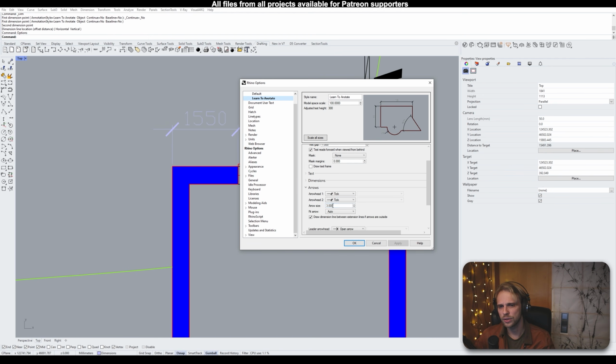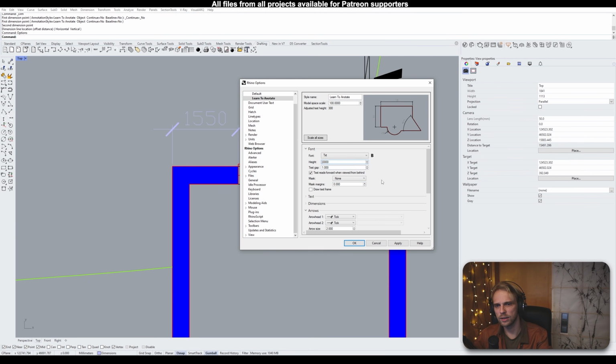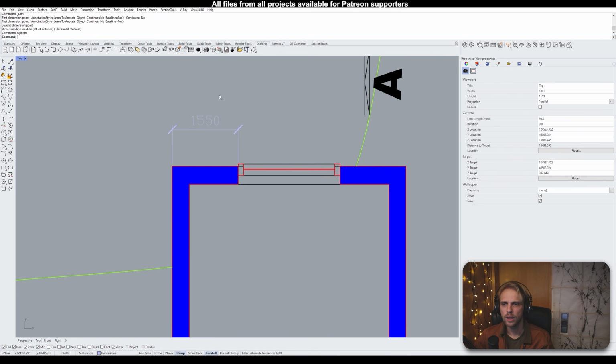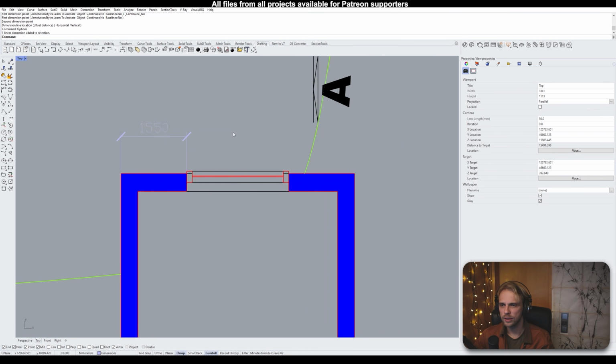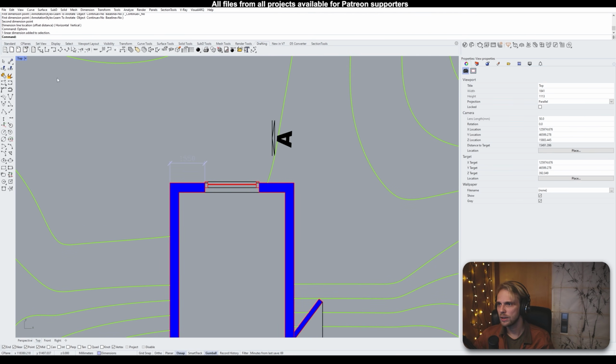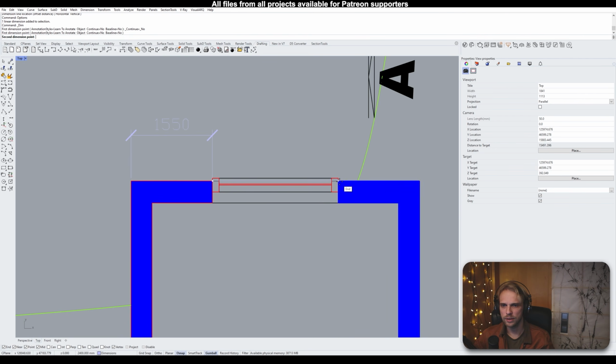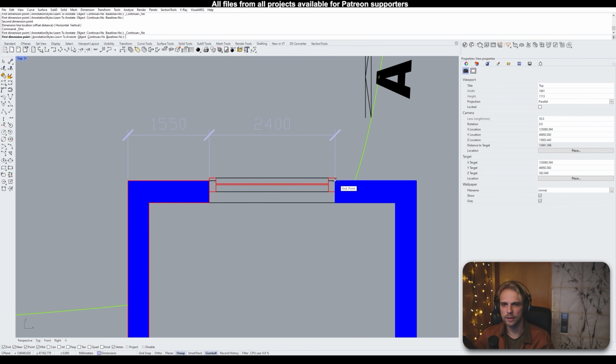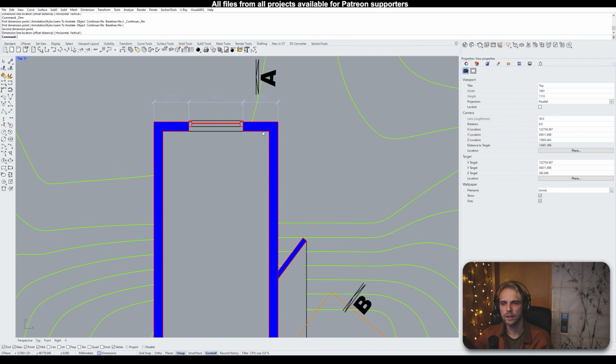If you want to change the arrow size to something a little bit more reasonable, like 2 millimeters, and perhaps your text height needs to be a little bit smaller, also 2 millimeters, then you can do it here, hit apply. This updates automatically, right? So we have our little annotation situation going on here. And that means we can now just go to linear dimension and just go to town, applying different measurements.